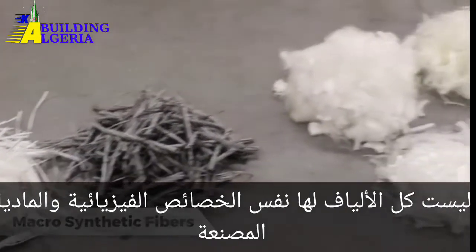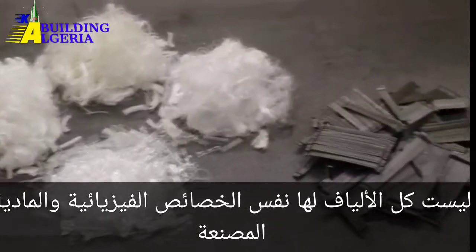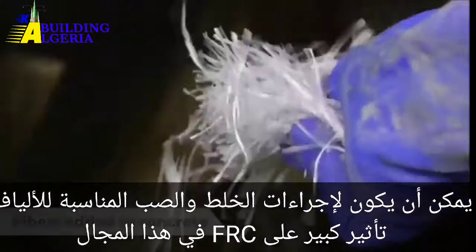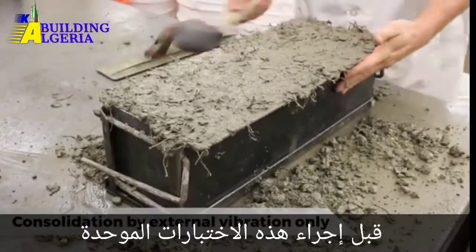Not all fibers have the same manufactured physical and material properties. Proper mixing and casting procedures for fiber can have a significant impact on FRC in the field. It is very important to maintain consistency and ensure fibers are properly distributed in concrete prior to running these standardized tests.